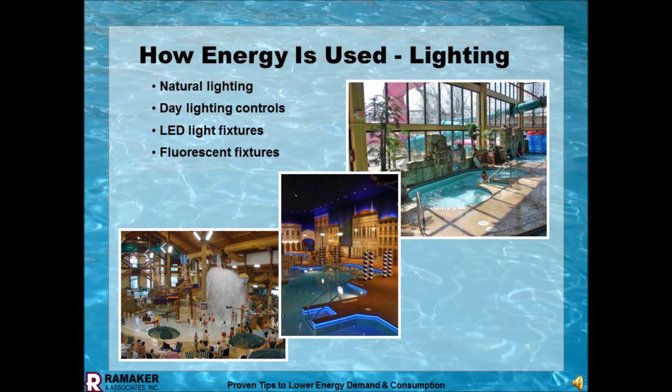This one's a little bit touchy in regards to how the pool was originally designed regarding the recirculation rate. When our firm designs water park pools, we over-design the filtration because we know it's going to get overloaded, and that's when you have your peak guests in there. I'm trying to anticipate what's going to happen on that Christmas holiday week when the water park is packed and the hot tub is running at full capacity all day. That water's going to get dirty, and in Wisconsin, they want hot tubs running at maximum 30-minute turnover.